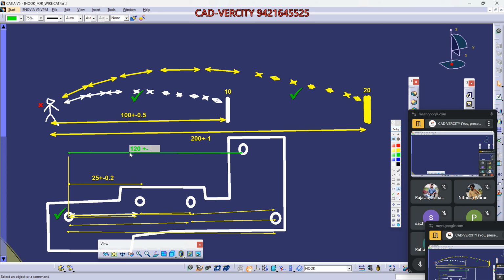Okay. See the same example as above. If we are increasing the distance, we will need a little bit more tolerance because there will be some error from this point till this point. So let's take 0.5 or 0.6 for now. As we increase the distance, the tolerance value also increases. Okay, sir, but I don't want to mention this dimension. The 0.6 tolerance is too much.